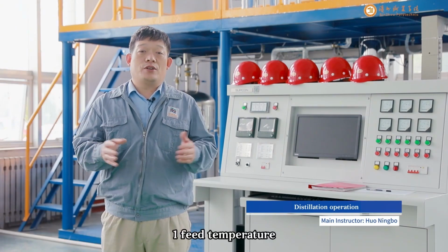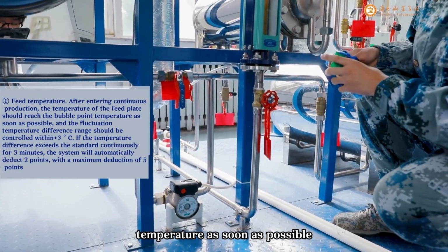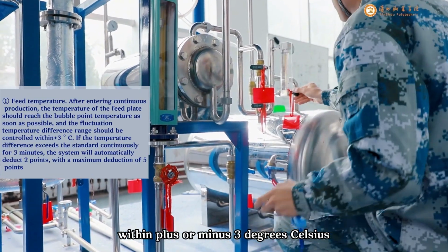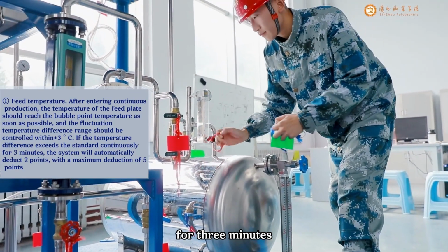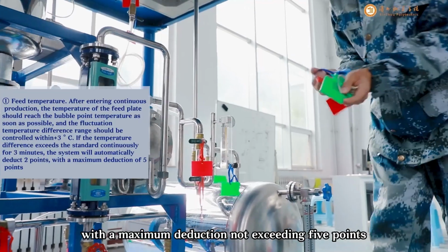1. Feed temperature. After entering continuous production, the feed tray temperature should reach the bubble point temperature as soon as possible, and the temperature fluctuation range should be controlled within plus or minus 3 degrees Celsius. If the temperature deviation continuously exceeds the limit for 3 minutes, the system will automatically deduct 2 points, with a maximum deduction not exceeding 5 points.